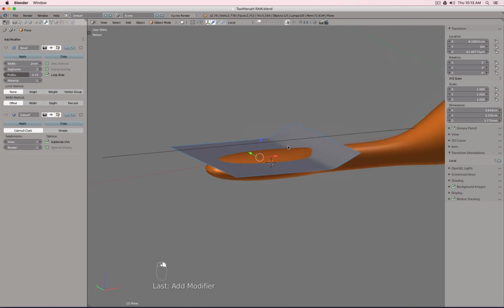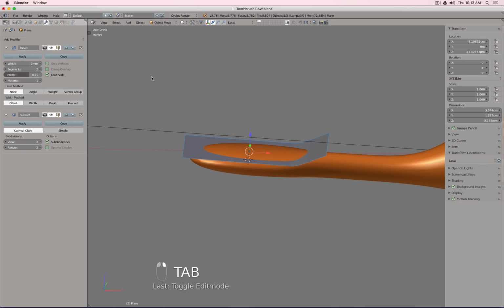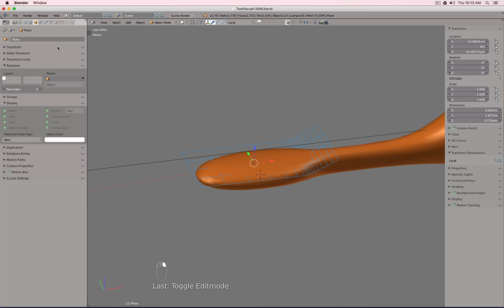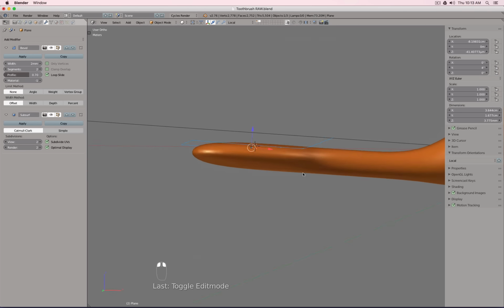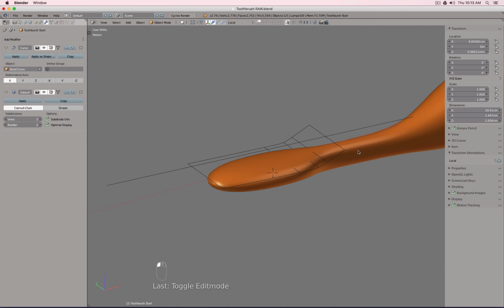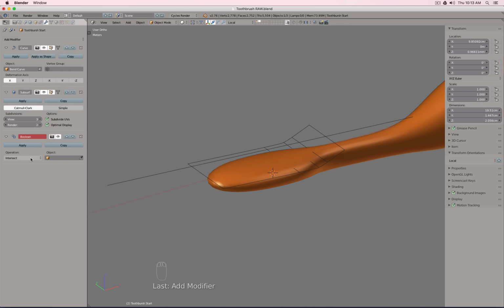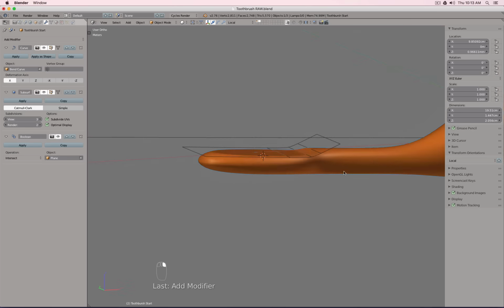Perfect, good. So let's scale this one down so I only see really what I need. This object is also currently visible, but I want to see where it is, so I set it to wireframe and optimal display, and then I can select this part and say Boolean difference, and this one, oh, okay, intersect for that moment.